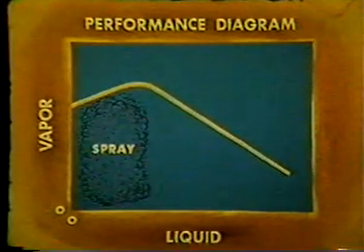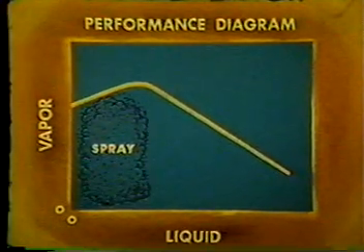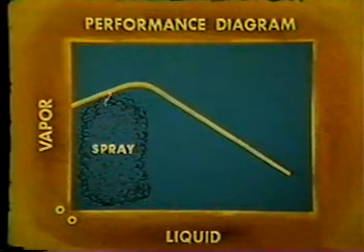Of the various regimes of flow, the spray regime is likely to exist at the low liquid rate and high vapor rate region. Distillation performed under vacuum conditions is usually operating in the spray regime.